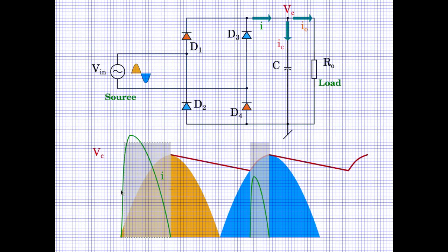What if at the time of turn on, the turn on was not synchronized with the 0 of the input voltage, but occurs somewhere here, which means the turn on occurs somewhere at this point, which means that the capacitor voltage is 0 and the grid voltage is pretty high, and you are connecting two potential devices together. There could be a huge surge current.